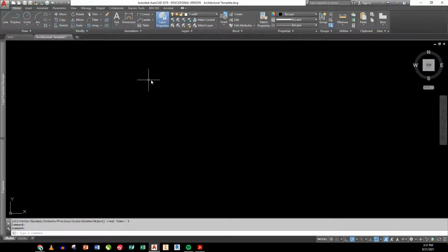Okay. So I'm on one wall still, and I'm going to just simply start with a polyline, and my units and limits are already set. And I'm literally going to go in here and start with my floor plan at the front of the house and work my way around. I'm actually going to start on what would be the lower right-hand corner of the exterior wall. Now, this house does have a brick veneer, but I'm drawing to the stud, the finish wall on this.